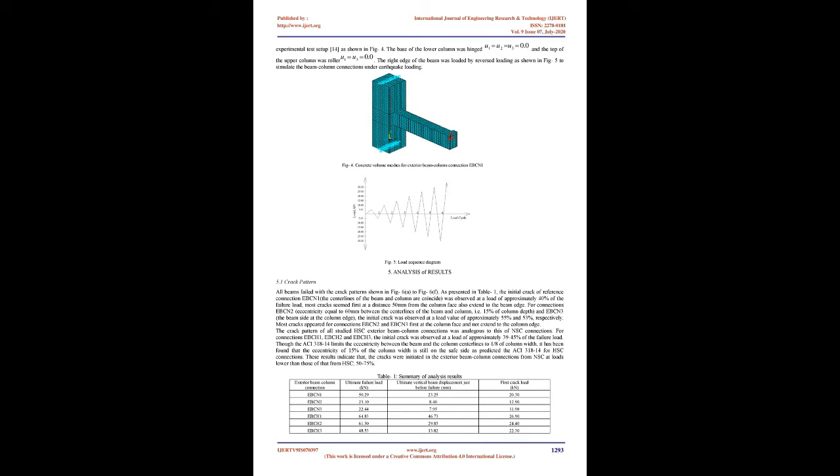4.4 Concrete. The elasticity modulus of concrete was calculated according to the ACI 318-14 formula, which gave values of 23,500.0 MPa and 35,652.04 MPa, for concrete with f'c equal to 25 MPa and 75 MPa, respectively.